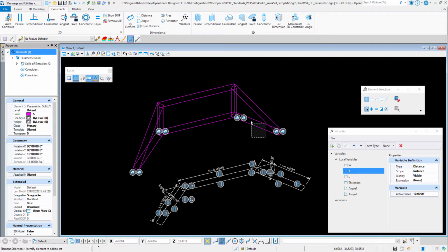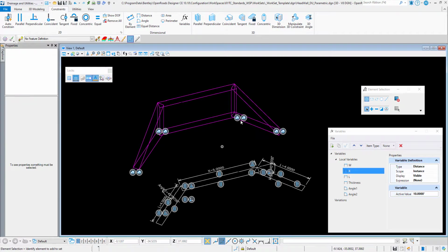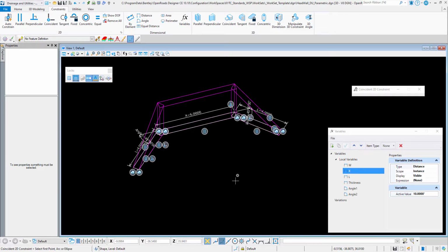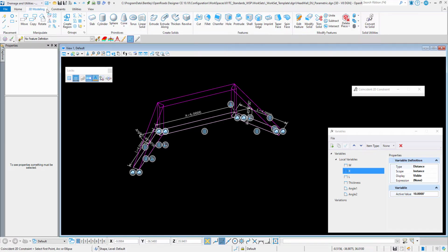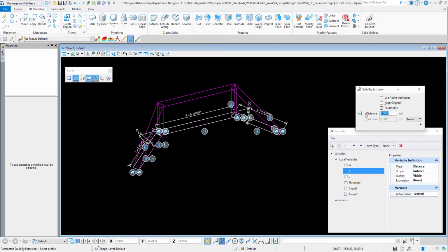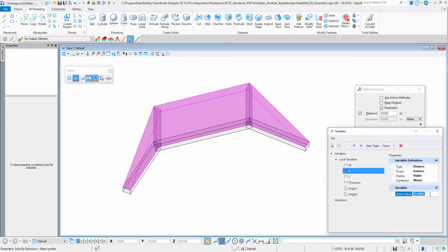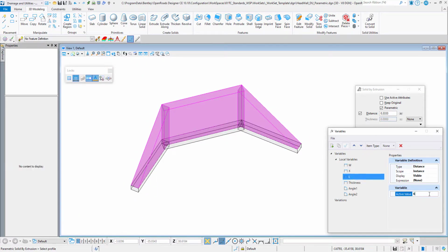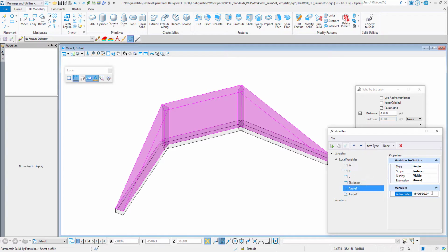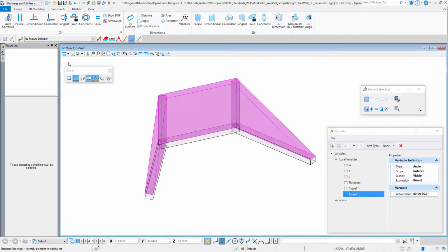And I'm going to select them just to make sure that I only have one element selected in the properties dialog. And then I'm going to use a coincident and affix the new shapes that I drew to the old shape, to the old solids. And then extrude all of them downward the thickness of the collar, which happens to be 4 inches. Again, always good to test. Change my lengths, change my angles, make sure that it behaves appropriately.